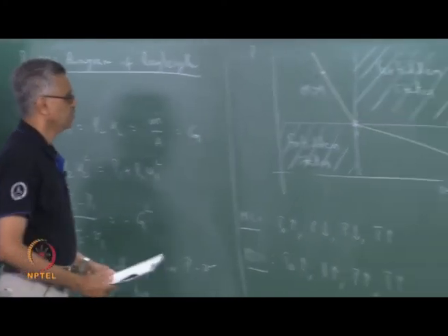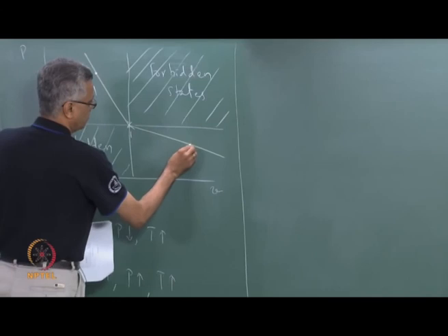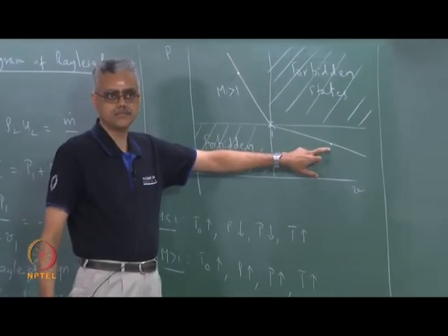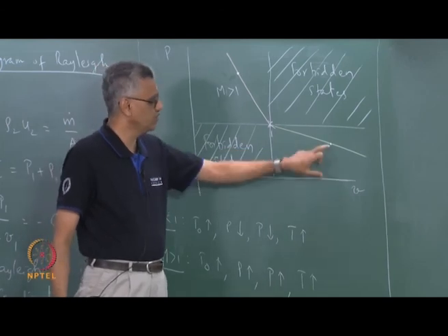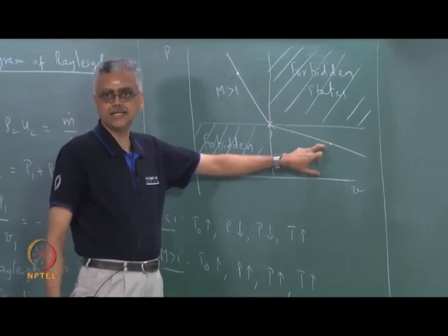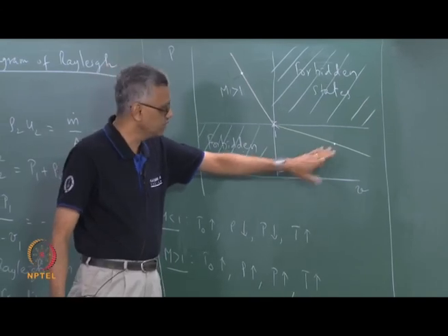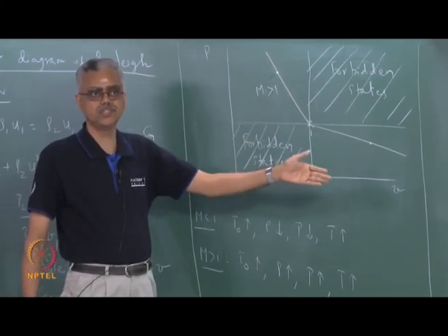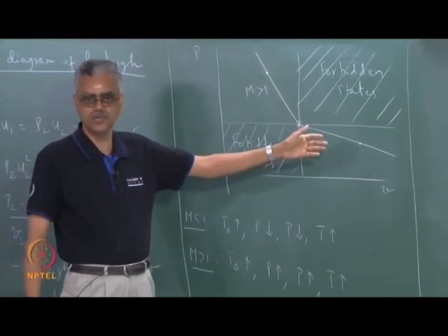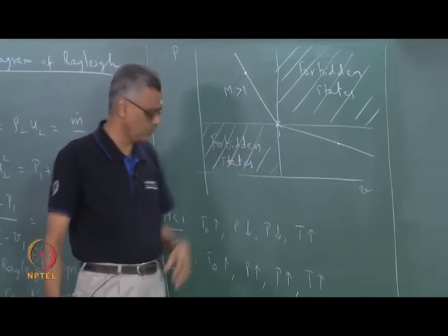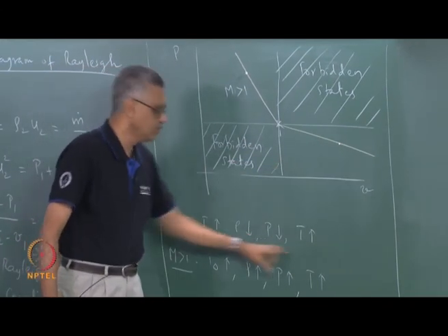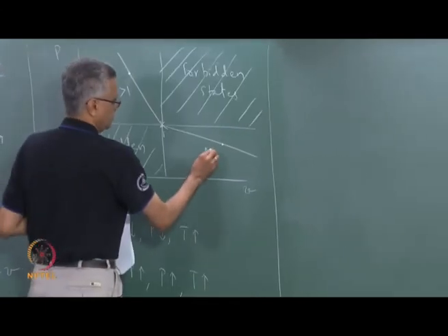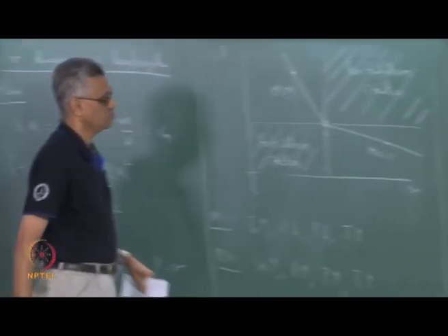Okay. So, similarly here, if state 2 were to lie, let us say somewhere here, then obviously pressure has decreased, specific volume has increased, which means density has decreased, and static temperature has, in this case, if it is so far down, static temperature could have actually decreased. That depends upon the shape of the isotherms. In general, the static temperature would increase, depending upon the shape of the isotherm. So, this corresponds to the subsonic portion of the Rayleigh line.